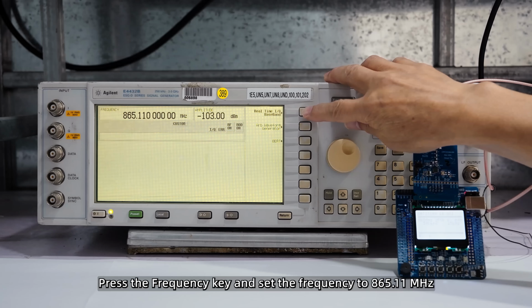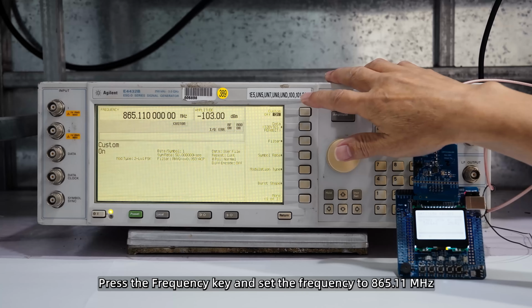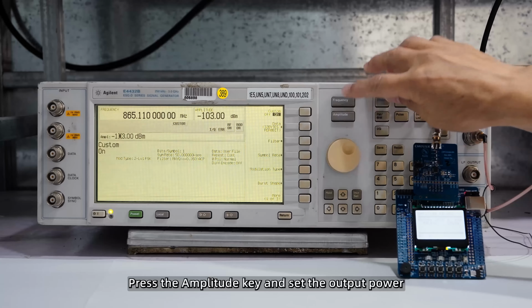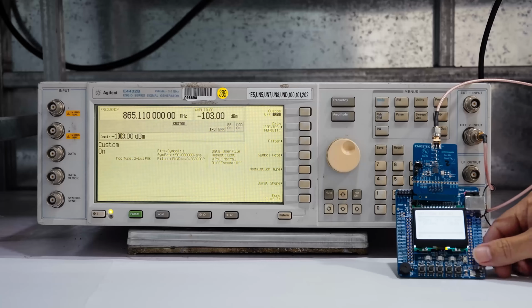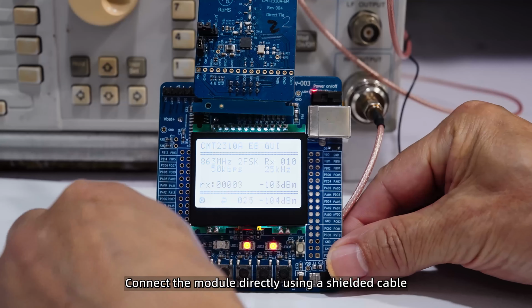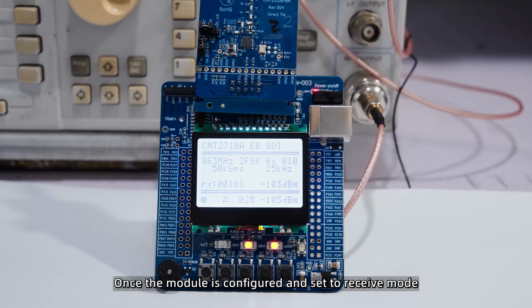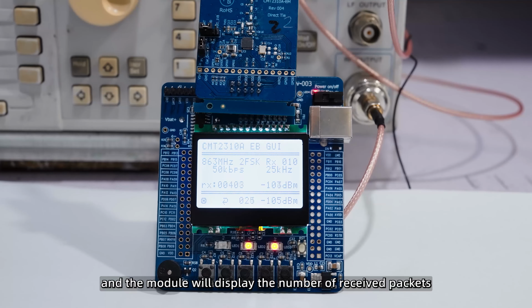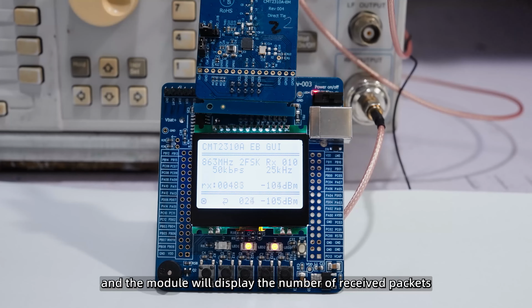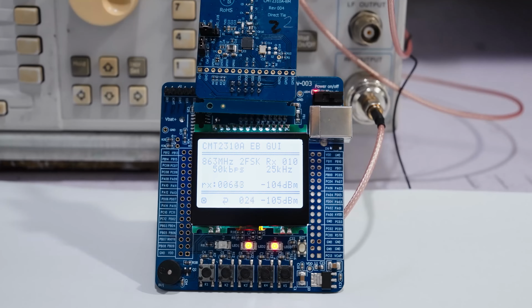Press the frequency key and set the frequency to 865.1 MHz. Press the amplitude key and set the output power. Connect the module directly using a shielded cable. Once the module is configured and set to receive mode, it will receive the packets from the instrument, and the module will display the number of received packets, the RSSI, and the signal-to-noise ratio.